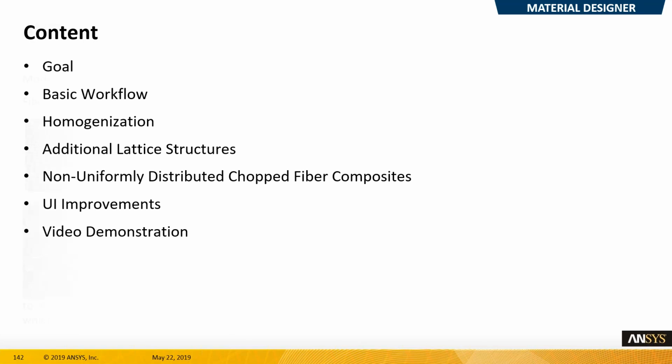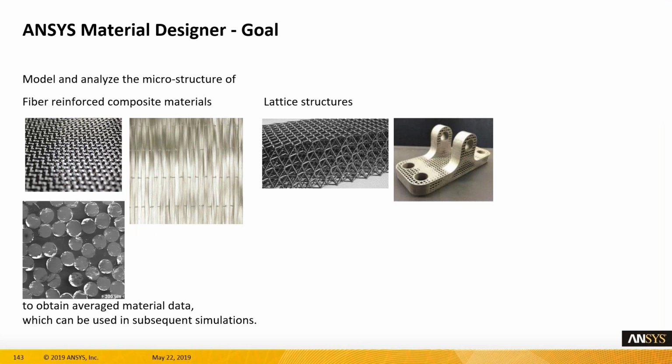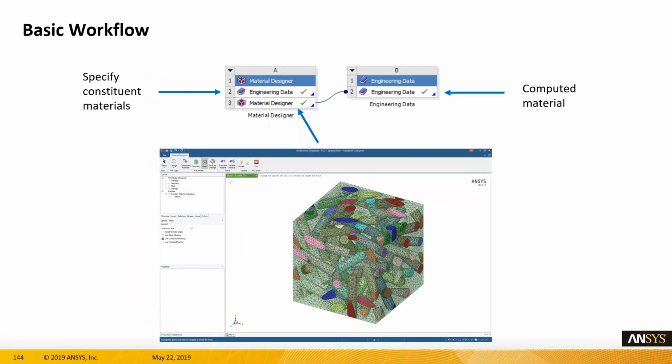The goal here is that when we apply two different kind of materials, we need to find equilibrium or common orthotropic properties. These normally have to be calculated outside ANSYS, either in a database or in your own Excel sheets, but now you have the ability to make very complex lattice structures or fiber orientation structures or fiber mapping, and then get a very exact result from this microstructural calculation. The whole calculation runs in SpaceClaim, so this is a layer on top of the already known SpaceClaim environment.